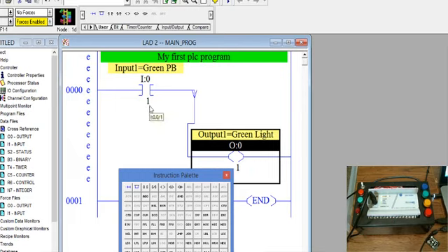With this, let me explain how addresses work while I'm here. The way addresses work for this particular controller is that I is the designation for input, 0 is the designation for the module, in this case a single compact PLC, and 1 is the designation for the point of contact or terminal. So in this case, it is an input, the single module or processor, and then point of contact or terminal 1.